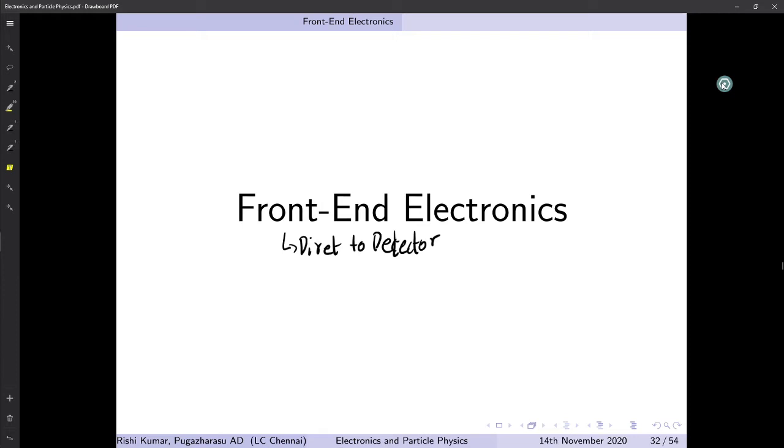Just to give a brief overview, the voltage preamplifiers match the input and output impedances to the detector output and to the circuits that follow right after the detector. So they're basically trying to ensure that there's no signal loss. The key aspects are gain, noise, and bandwidth. They're very similar to the regular op-amp circuits that we've studied. The current amplifiers behave very similarly, but instead they take current as the input, and the charge amplifiers integrate the detector output.